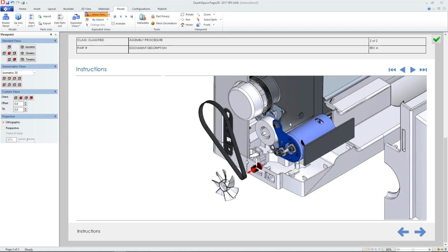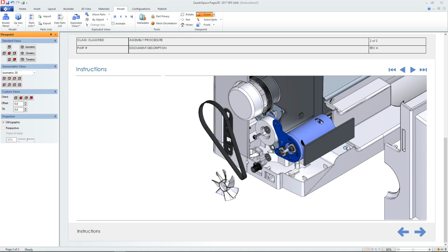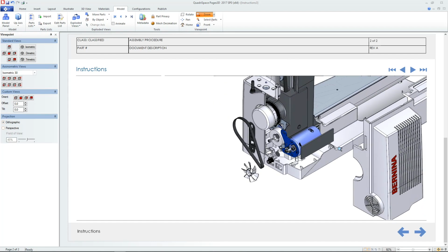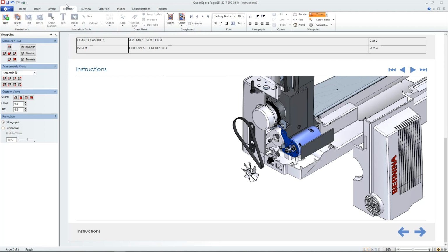We can select multiple parts using the model tree or by holding down Control after selecting the first part. Additionally, you can type in specific distances or rotations instead of using the mouse. This template is preset to animate between illustrations using the interactive play bar at the top.